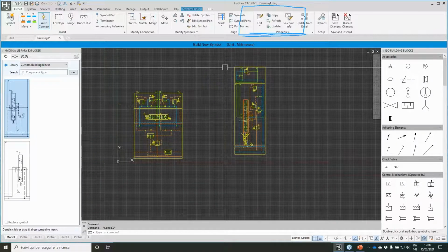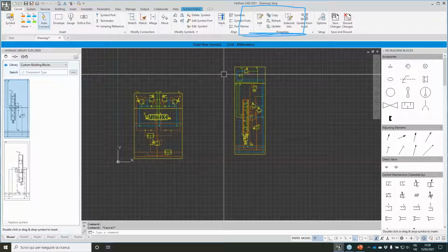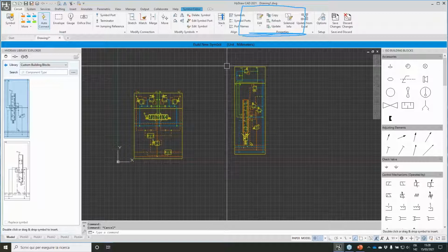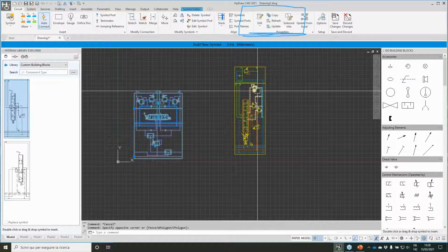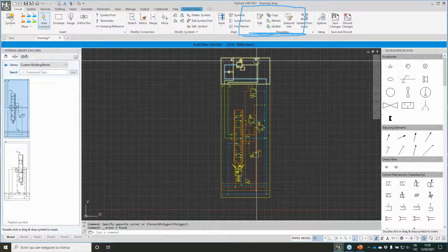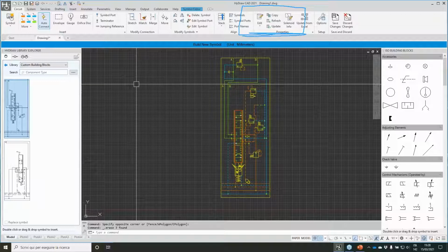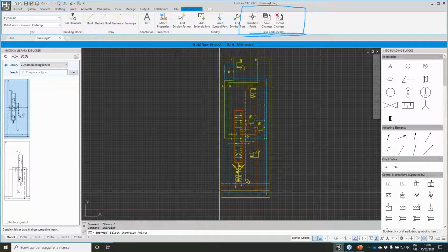It is important that all these items are usable in a HyDraw part list. So, for instance, I want to save this block. Now, I use these dynamic blocks to build my custom section of a sectional valve. And now I just want to define the insertion point of my element.